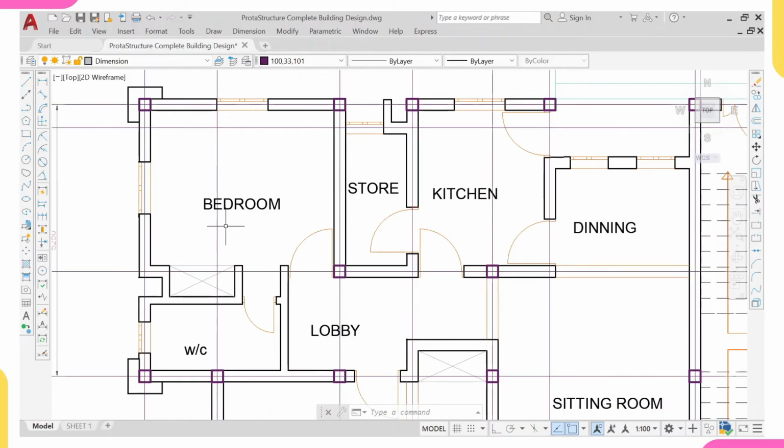But if this panel is more than 30 meters square area, there are 2 things that you can do. Either you increase your slab depth, that's you might move from 150 to 175, or you introduce a beam here to demarcate this. So here will be one panel and here will be one panel. So it's either you increase your slab depth or you introduce a beam to cut this slab. Maybe you introduce a beam here and a beam here, so you divide this slab. Here will be one panel and here will be one panel.